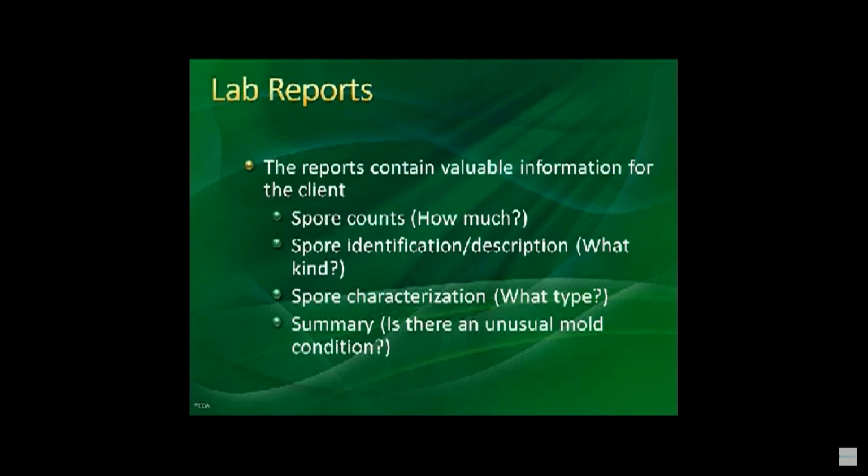Then we'll get lab reports. Once you pack everything up and you learn how to mark down your sampling medias to send to the lab, which we'll teach you, you're going to send it to the lab. The lab is going to give you a report that's going to tell you how much mold was there, what kind it was, what type, and some of the labs will actually do interpretation and say that there is an unusual condition.